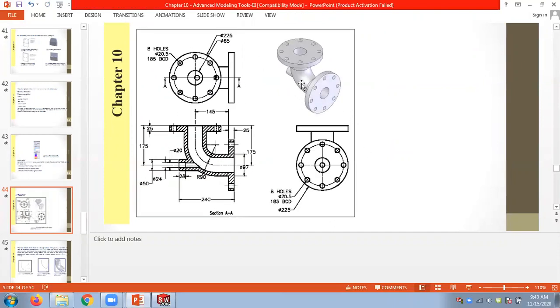So immediately you have to notice that this uses the sweep tool. Because the path is a bend, you cannot take it from extrusion, you cannot take it from revolve. So straight away you need to understand what to draw first. Normally we don't need to draw these flanges first. We can draw the base feature. So you have to understand what is the base here, the foundation. The foundation is this middle tube. So we need to start with this middle tube and draw this flange.